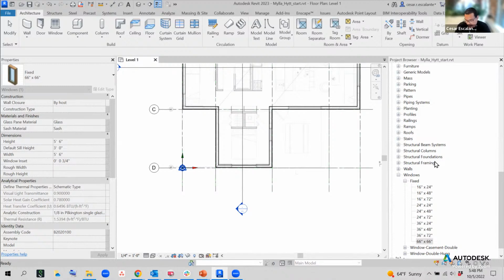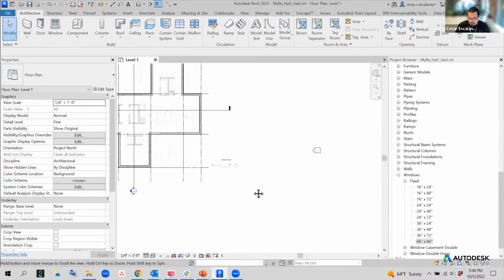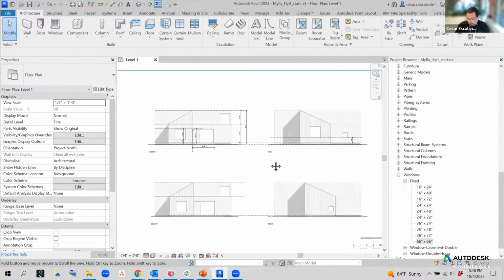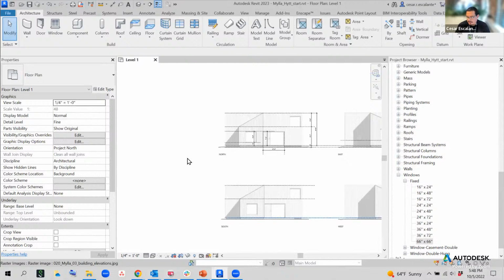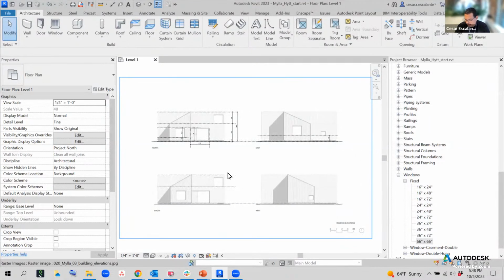It's an available type that you can drag and drop into the project. Any questions here? I think we wanted to change the sill height to 3'6" or 3.0. If it's all clear, now do one on your own. Create the 2.6 by 2.6 window, a 30 by 30, and I'll give you a couple of minutes to do that on your own. I'm not going to give instructions because you know how to do that, right?